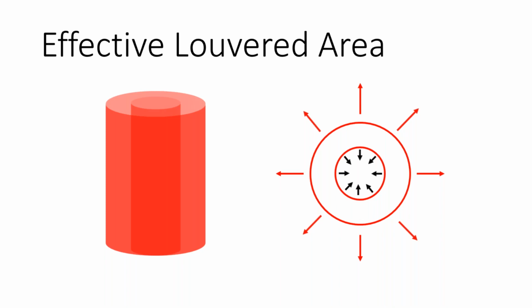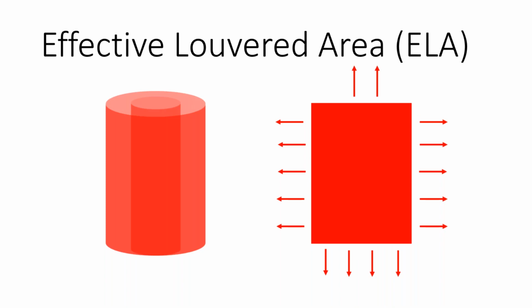With the example of the grain guard, or with the rocket, the outside louvers go directly into the grain mass, but the inward louvered area is going effectively into a dead end. And the way out of that dead end is either going upwards or going down. So it has a slight reduction in the overall louvered area because it isn't an efficient path for the air to follow.